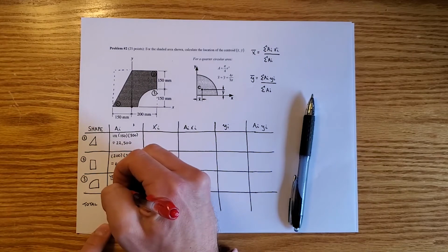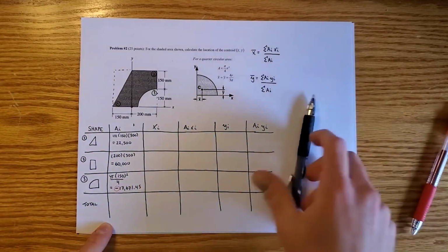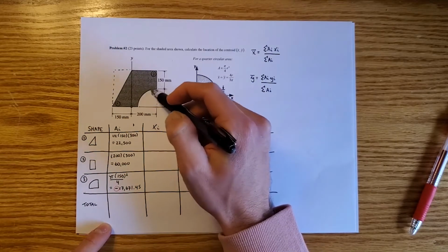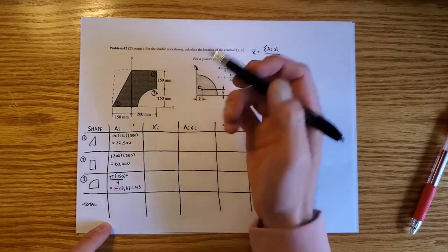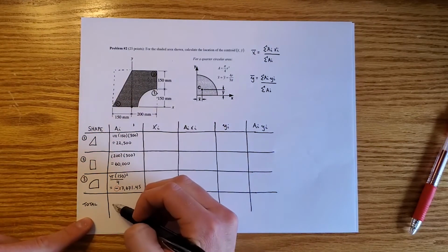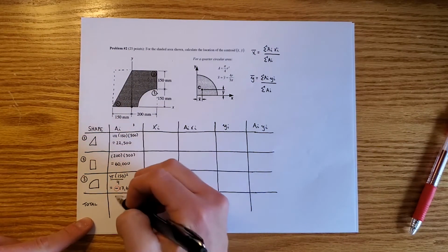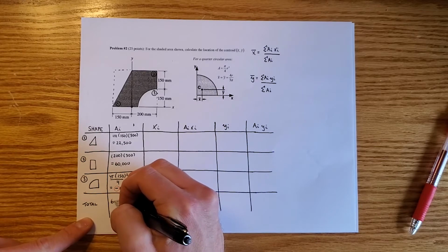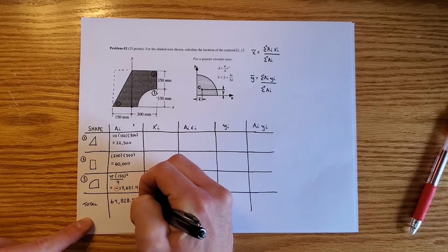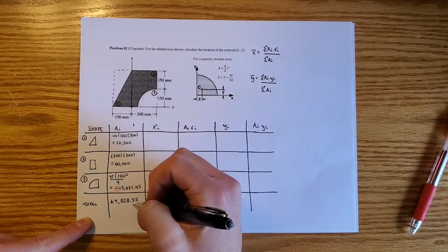Now, something I want to point out that's actually fairly important in these types of problems is that I've made this negative. The reason I've made this area negative is because this isn't actually a part of the shape. It's a piece that's been omitted from the overall shape. So the area should be negative. So when I add up the areas in my total row, I'll get that the total in this column is 64,828.55